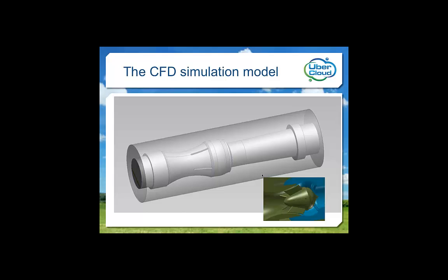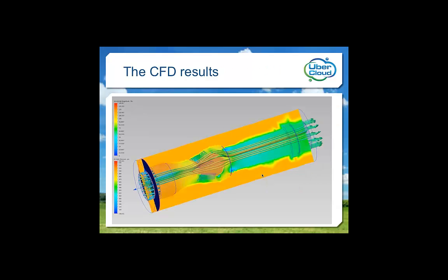Following standard practice as a new user, I set the flow rate to 500 GPM, the upstream pressure at 500 PSI, entered the data requested by prompts, left alone the default settings for meshing and solution, and clicked Solve on my local workstation. The cross-section plane shows the distribution of the pressure at the fluid boundary and about 450 psi-G at the discharge.